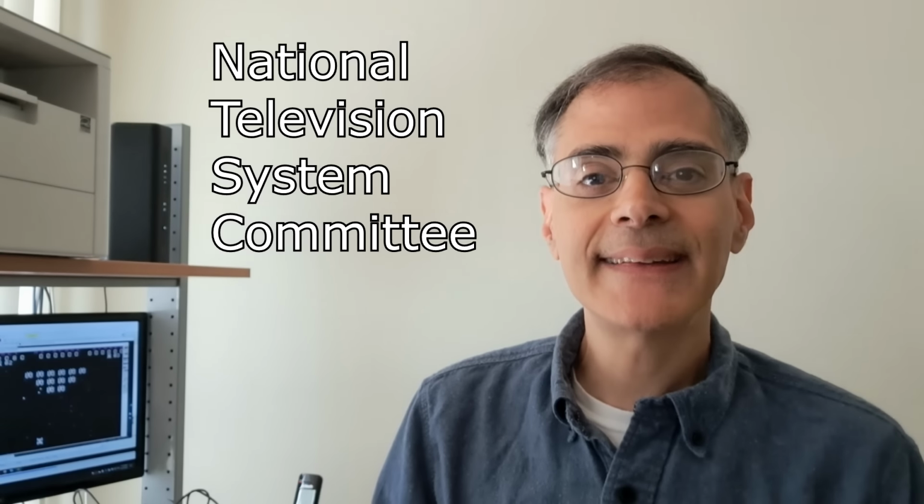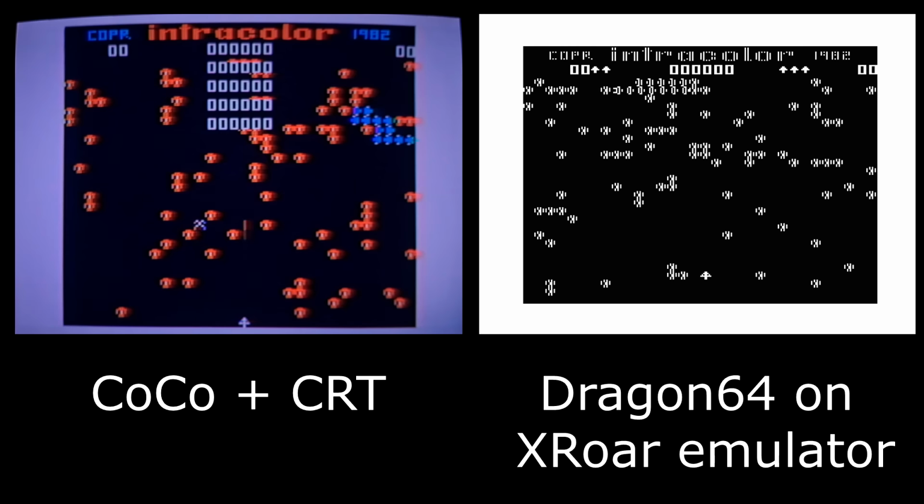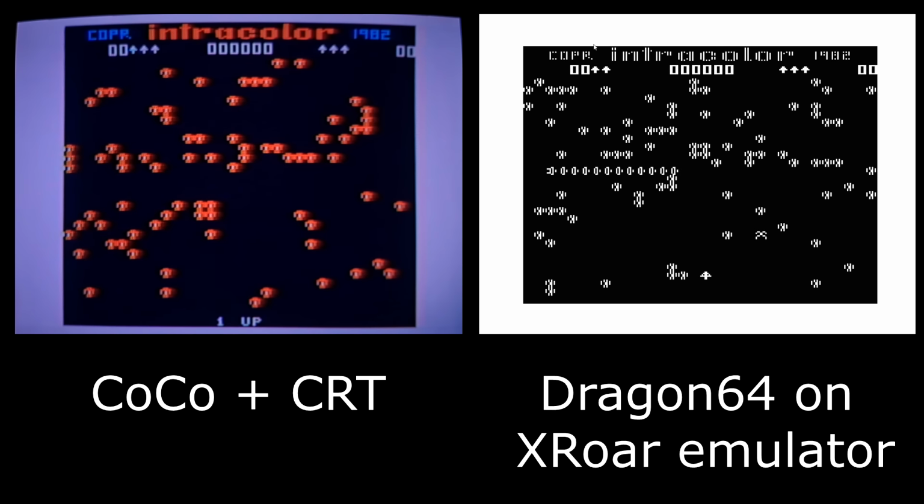So let's dive into TV signals. We will specifically be discussing the standard set forth by NTSC, popular in North America and parts of Asia. Different regions had different standards. So for example, if you lived in the UK and your CoCo or one of its cousins like the Dragon used a PAL system like PAL-I, rather than seeing the NTSC artifact colors, you'd see the original black and white image generated by the software. This is not to say that NTSC was the only standard that had artifact colors, but it was particularly cheap and easy to take advantage of color artifact colors with NTSC.